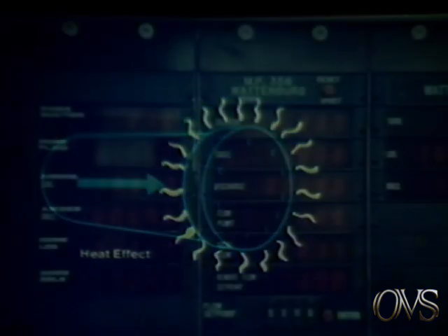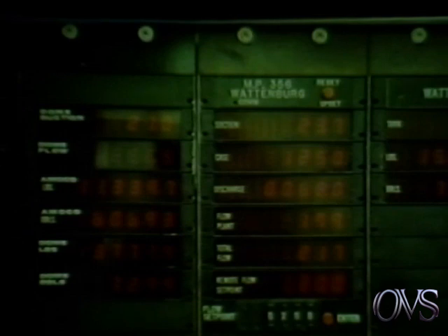To avoid the hazards of either heating effect or pressure shock, static lines at low pressures should be gradually raised to operating pressures, rather than being boosted to full operating pressures in under a minute.